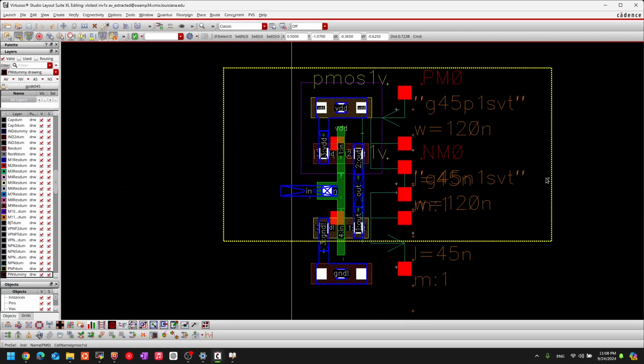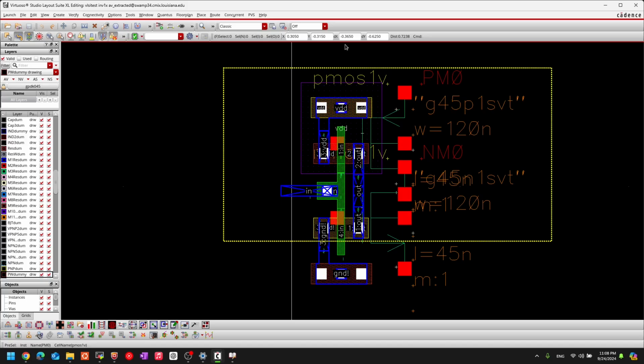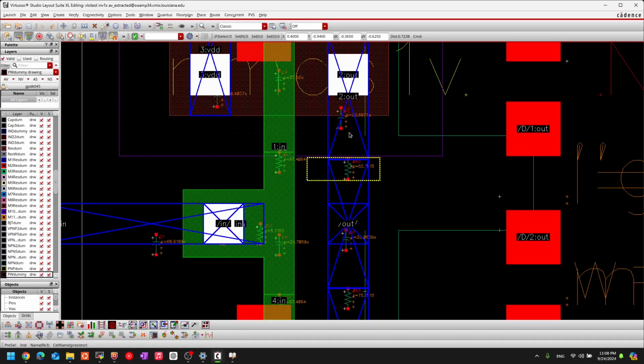Once we did the RC extraction, we will observe these results by doing analysis on it. I will show you how to add this onto the environment when you want to simulate the circuit based on this structure rather than the ideal one. Because when we built the schematic at first, it didn't include these small capacitors and small resistors.